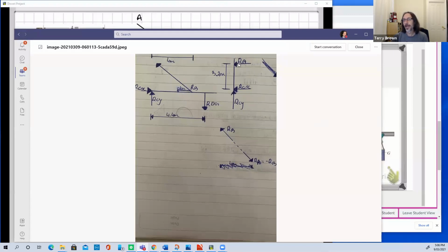Also up here at A, you've got this as a horizontal force, okay? Because this cable is a two-force member in equilibrium, the line of action of that force is along the line A to B, okay? So this force RA here will be along that line. So same as you've got drawn here. So I assume this is your free body diagram for your cable, although you got RA and RB swapped around.